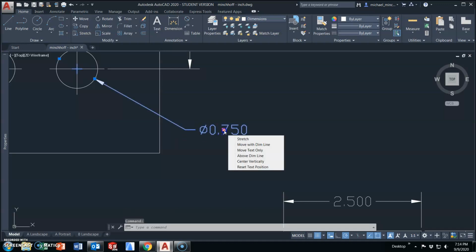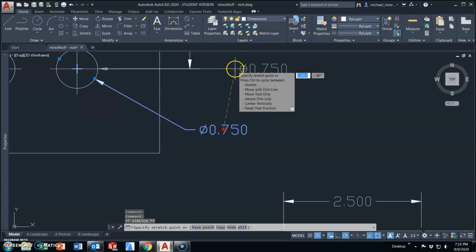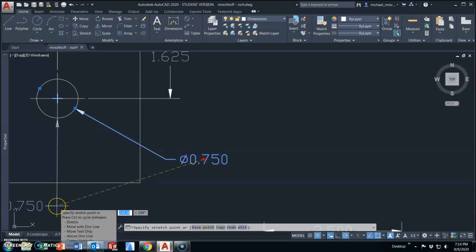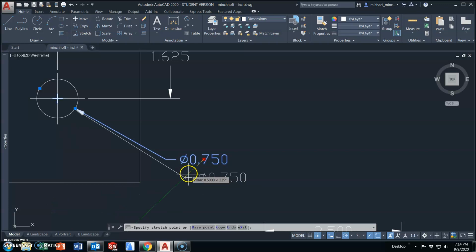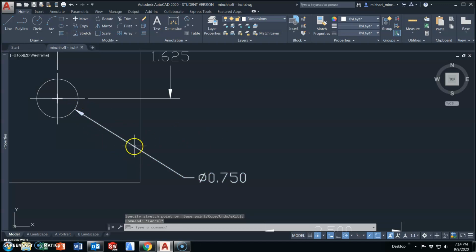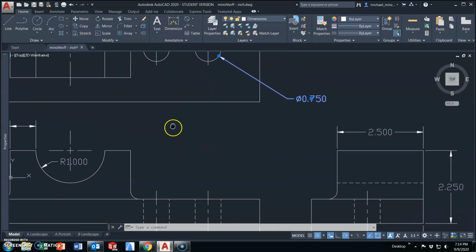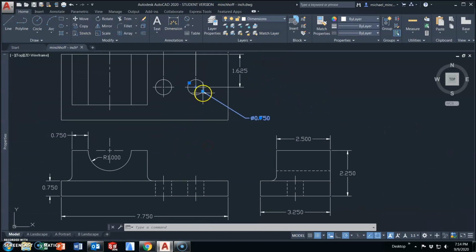When dimensioning arcs and circles, there are just a few rules you want to keep in mind. Do not dimension horizontal or vertical. The leader line blends into the center mark, and this is just from old drafting standards. When you had your triangles, you can make any combination of 15 degrees. We don't need to make a measurement that this is a 15-degree angle on the leader line. It just can't be vertical or horizontal. It cannot be confused with any other dimension. We've avoided dimensioning on the object, and we have now dimensioned circles or holes and also a radius.